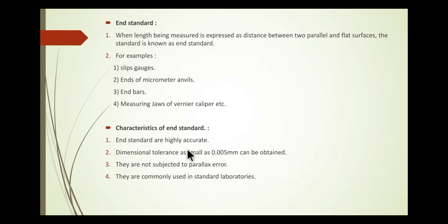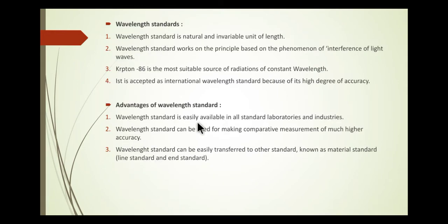Characteristics of end standard. First, end standards are highly accurate. Secondly, dimensional tolerance as small as 0.05 mm can be obtained. Third, they are not subjected to parallax error. Fourthly, they are commonly used in standard laboratories.